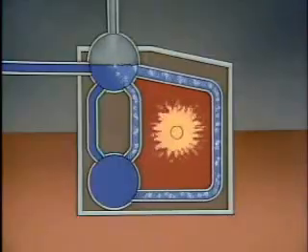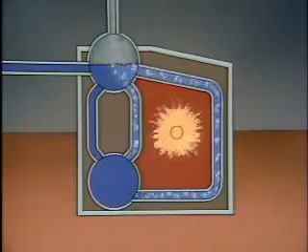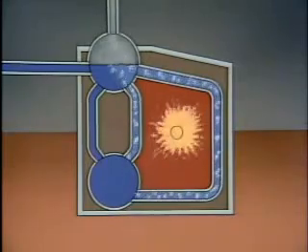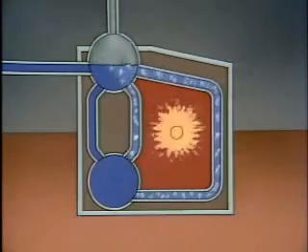With this type of water tube boiler, water circulation depends on the differences in density between water and steam. Mechanical devices, such as pumps, are not needed. This method of circulation is called natural circulation.